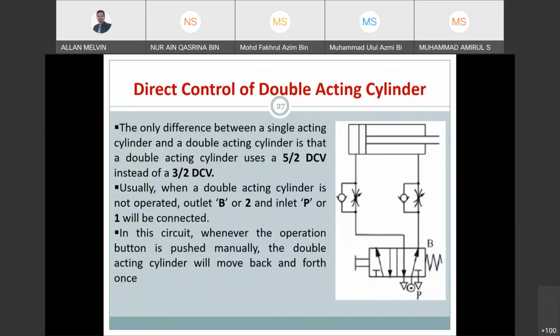Because when you troubleshoot the circuit, if you just use a normal roller, you'll have a signal conflict. Signal conflict meaning in the direction control valve, both sides you are getting pilot input at the same time. So your valve cannot determine which one to do. You give two inputs and tell it to decide, and you don't give it intelligence. Practically what will happen is both sides will receive the same pressure, so it cannot move.